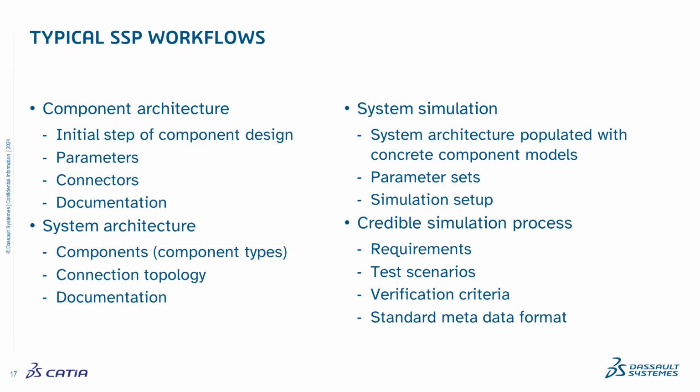Then we can go into more concrete system simulation. That's where the components are populated with concrete implementation of the behavior. You apply the real parameter sets and a very simple simulation setup. And then we can extend that further into what we call a credible simulation process, where you try to capture documentation about requirements, test scenarios, and verification criteria, using a standardized metadata format.